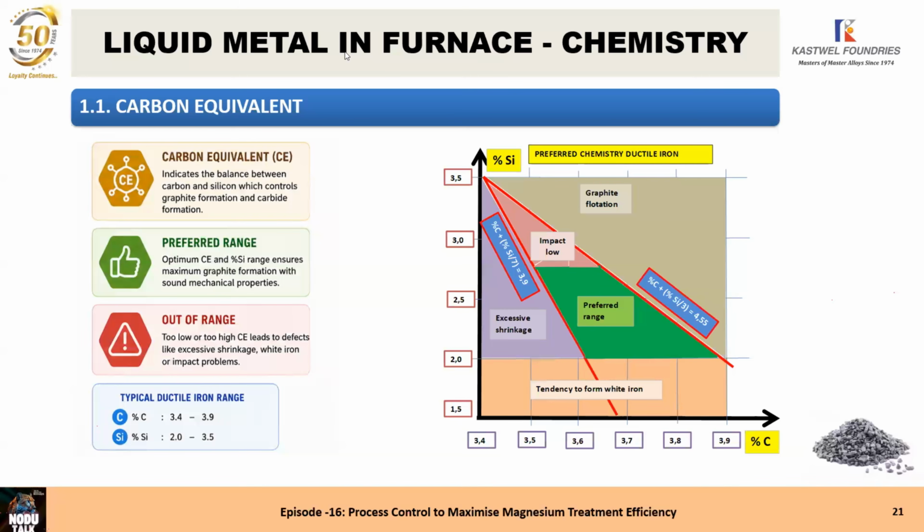Yeah, I agree, and I have to add something: the tundish cover treatment ladle is the one that gives the lowest loss of temperature. That's the first. Secondly, I sometimes see foundries where the distance between the furnace and the ladle is very, very big. In the beginning, when you start tapping, there is a very small amount of metal coming in contact with the air. It will decrease a lot.